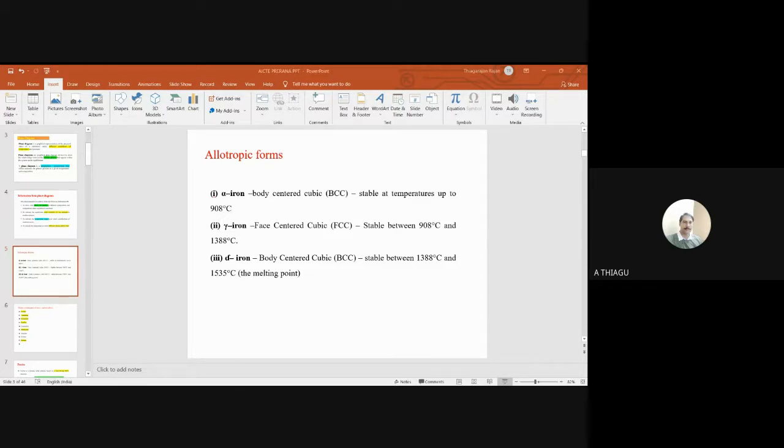So this is in the case of hypo-eutectoid steel, but in the previous case we could not find this transformation. Can you get the point? So below 0.8% of carbon, we get a different microstructure. So this is the essential thing. With less carbon, we find 50% conversion, and at 80% later all the austenite is changed to pearlite. So proeutectoid and complete eutectoid. So alpha.